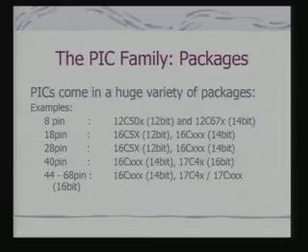Let's try to look at the family. In fact, it's a family of processors which have a variety of configurations. Here we have shown some examples with different numbers, because PIC is not just a single microcontroller but a family of microcontrollers. And these 12-bit, 14-bit, 16-bit, these are different word lengths that these processors support.